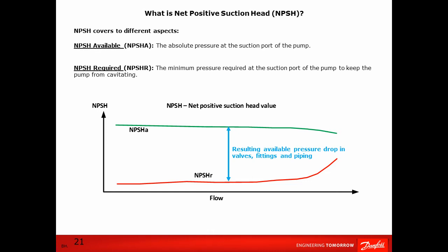Please note that the NPSHA curve reflects a water tank where the water level is constant. A drop in the water level will also affect the NPSHA value. This is highly critical and may cause cavitation of the centrifugal pump.